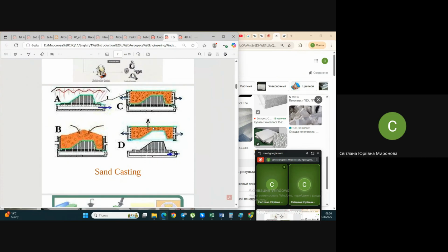In order to help material to be distributed equally and very quickly all over the surface of the mold, there are additional technological tricks, let's say, applied. One of the tricks is rotating of form, rotating of mold. Quite clear, it works only for axisymmetrical shapes, like pipes, for instance, or do you imagine something like a bottle, for instance? In this case, it works very well.